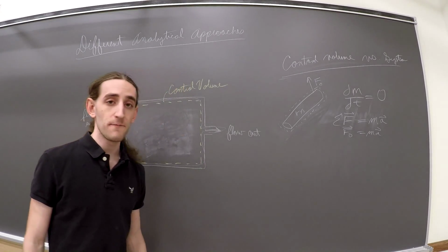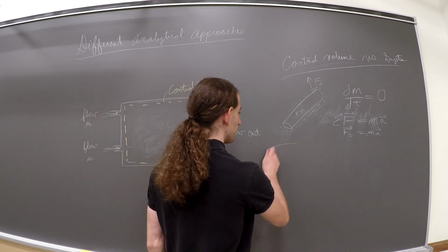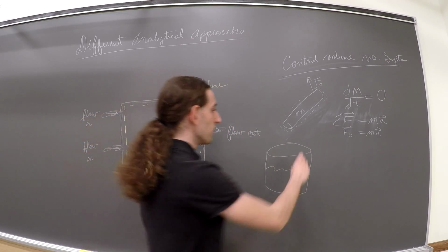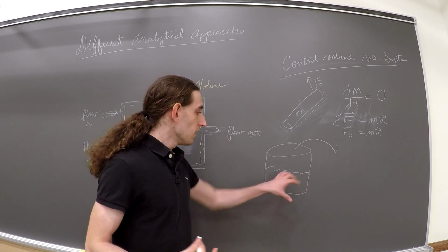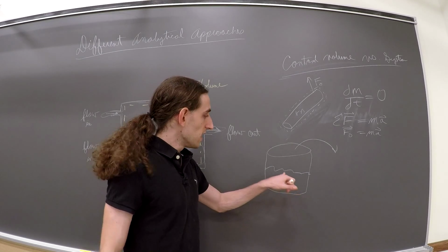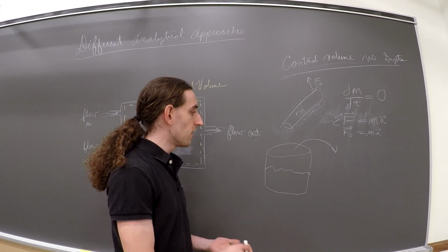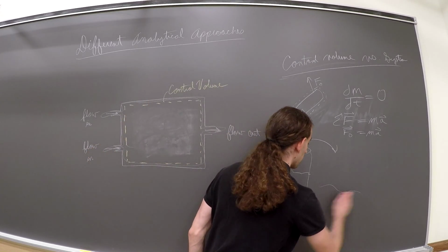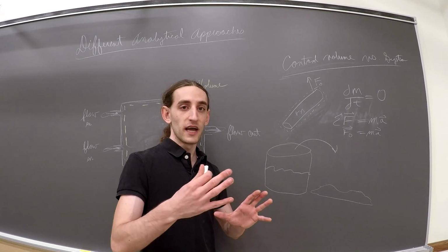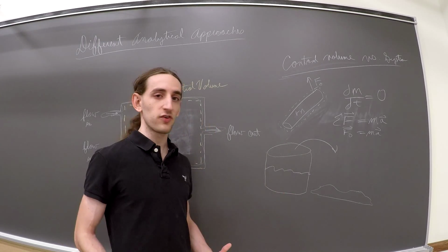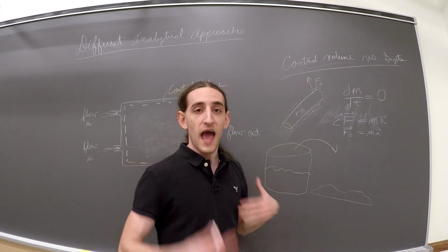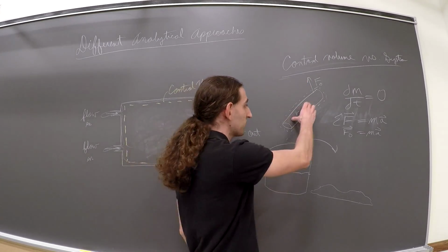They're not fixed, right? So, for example, if we take a cylindrical drum, we fill it up with some water, like so, and then we turn this and pour out all that water, then the system of particles we're analyzing, the boundaries are going to move, because the shape of this is not definite. It takes the shape of the container it's in. So as a result, we might have a ton of water on the ground, something like this, after we pour it out. And that's a different boundary enclosing the system, right? So as a result, we can't apply the conservation laws that we have from solid mechanics here, because these boundaries and the volume do not coincide with the mass we're analyzing.